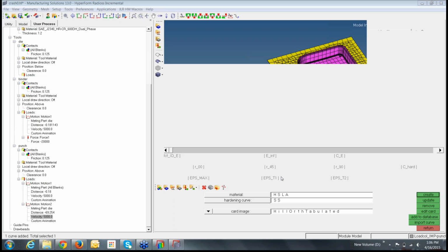So those elements will not get adapted, and it will add a non-structural mass to your blank such that your time step value will greatly reduce, and then your run times will improve. If a normal run takes 1 hour, it will finish within 15-20 minutes without any loss in your accuracy.